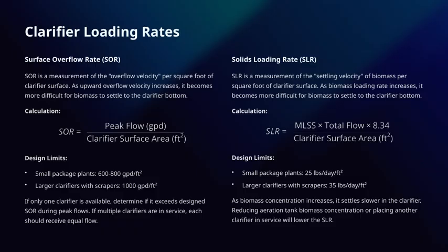The calculation here also depends on plant size. For small plants, the limit is about 25 pounds of solids per day per square foot. For larger clarifiers with scrapers, it's around 35 pounds per day per square foot.